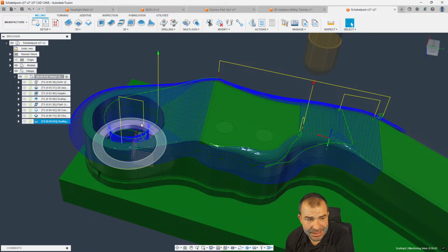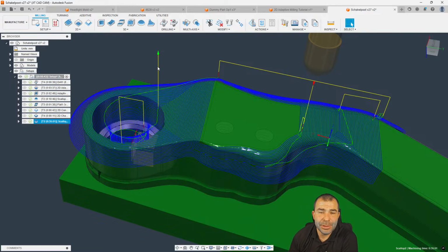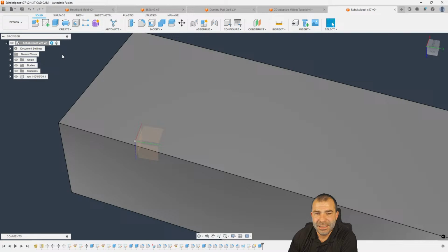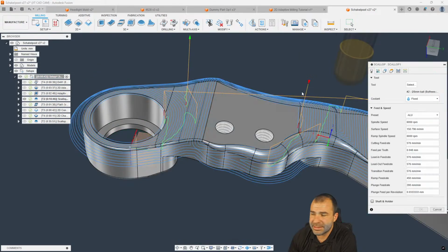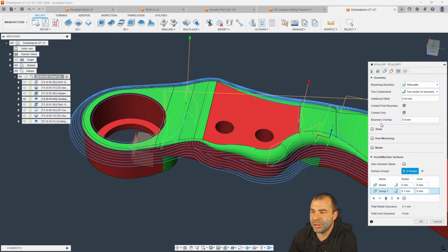So again, this is something I've started to see with the new Avoid Touch surface: I like to compare it more to the design workspace. Create your toolpath, then modify your toolpath, right? So the same concept, right? You go through your process, you've created the location of your toolpath. Now we can modify by changing slope. Do we want to go through and add additional models to avoid features, and so forth and so on, something like this?